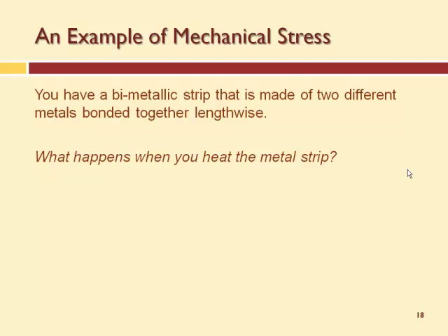Okay, so bimetallic strips, we've all seen those. They're in thermostats. Well, maybe not all of us, but some of us have seen those. You take apart an old thermostat, you're replacing it with a digital one. Take it apart, the old one, you'll see a coil, and it has two metals on it. And if you take a lighter and heat it up, you'll see the coil either unwind or tighten up, depending on how they designed it. And those bimetallic strips, what happens is one metal expands at a different rate in temperature than another.